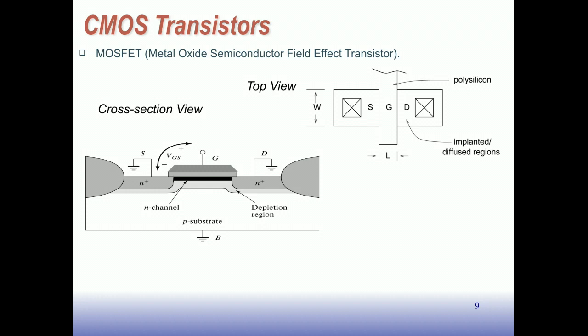In cross-section, the transistors end up looking like this. And this is kind of an old story. FinFET has changed this a little bit, and I'll show you a little bit about FinFET. But this is the old so-called planar transistors. And here's the source region here, and here's the drain region. And these are regions that are down into the surface of the silicon. And then there's a gate region that sits up here.